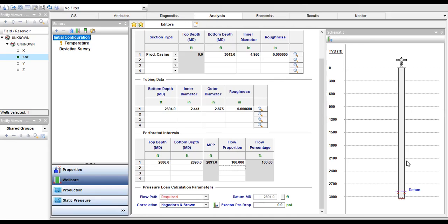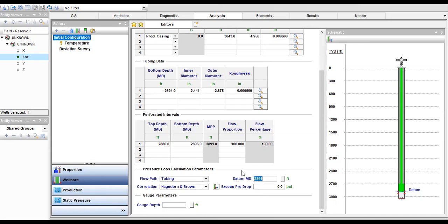You see, the picture is still blank like that because we haven't used the flow path, that gas and liquids take from the producing formation to the surface. So let's click on this one and see there. The green color shows the flow path zone. There must be the annulus, the casing side after the tubing. And then we have our perforation. Okay, so change it manually if you want. Like this, you can type the datum that you have, but I will leave it as it is.